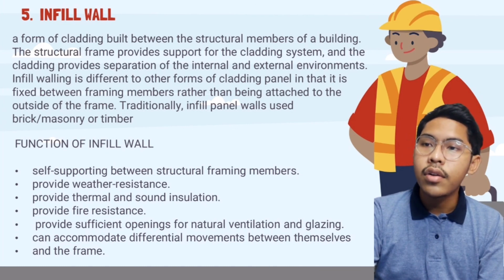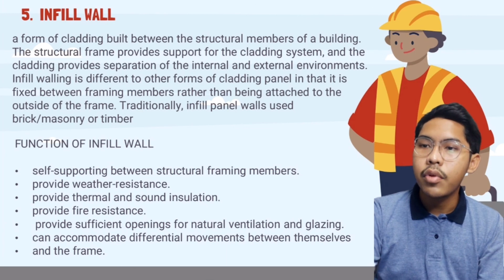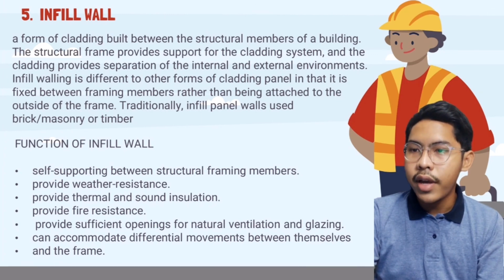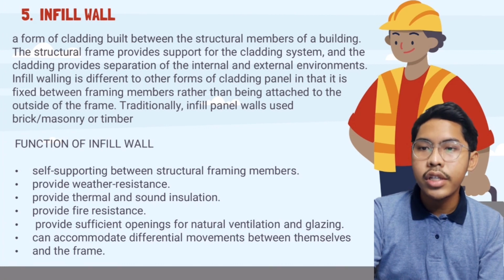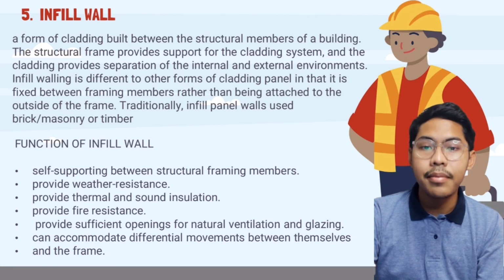And the functions of infill walls are: to be self-supporting between structural framing members, provide weather resistance, provide thermal and sound insulation, and provide fire resistance. Next, provide sufficient openings for natural ventilation and glazing, and accommodate differential movements between themselves and the frame.